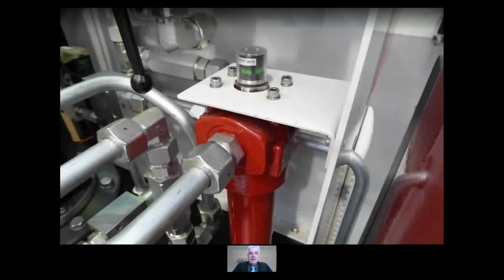Okay, so we have a photo here of a typical pressure filter housing with a visual indicator. Visual indicators are very, very common. I would suggest, though, that they are only really useful if someone's watching. If someone's looking at that thing, they can tell the state of it, and that's really what it's for. But if no one's there, because this filter's on a vehicle that's moving, there's no one there watching it, then maybe you need an electrical indication, and that's going to tell you something you can't see. So that's a better form of monitoring, more common. So visual indicators are fine if someone's watching.